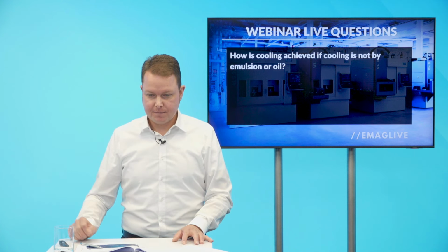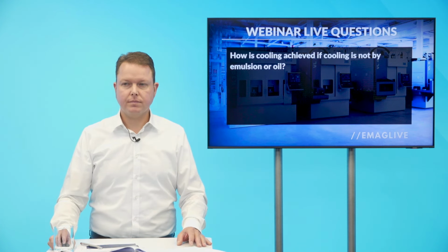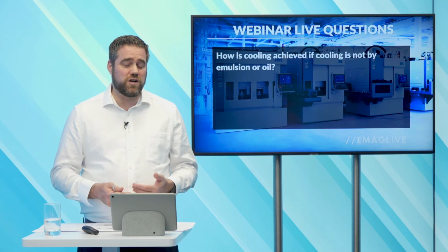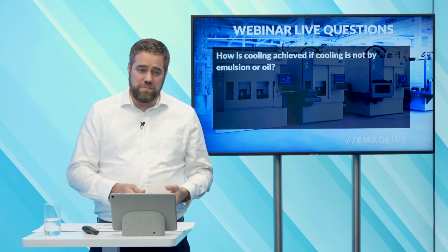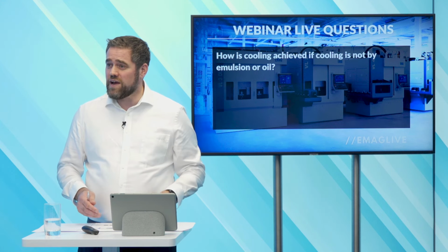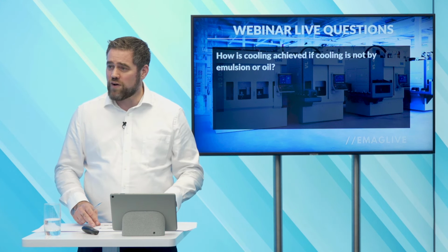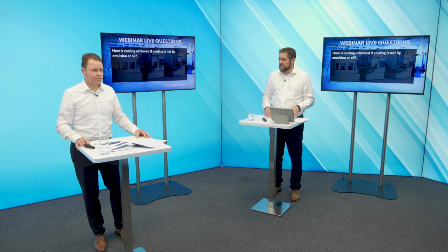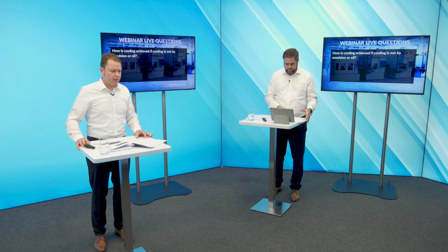Okay, and if I add shortly to this slide something, what is important of sure, if we do dry hobbing, should be the goal as well, that the pre-manufacturing steps or the pre-processing steps should be as well under dry conditions, because then otherwise I need to wash anyway. So that's also I think an important point. Yeah, absolutely, you're right, Heiko.